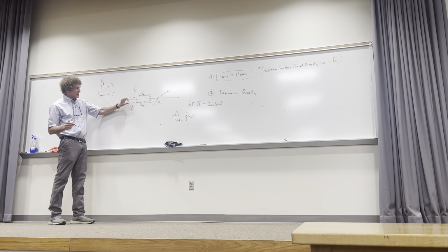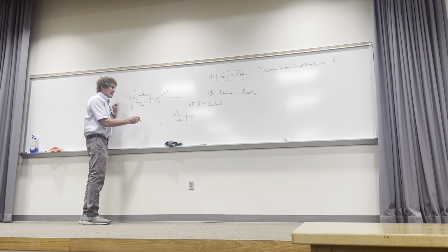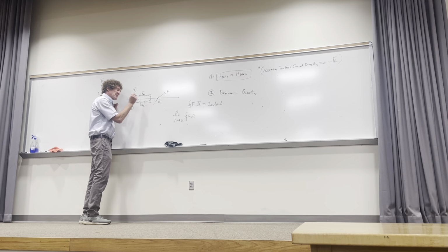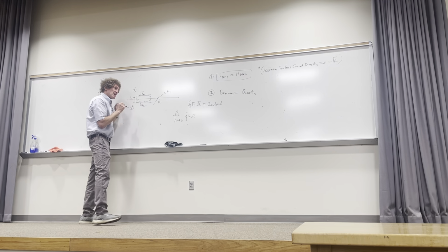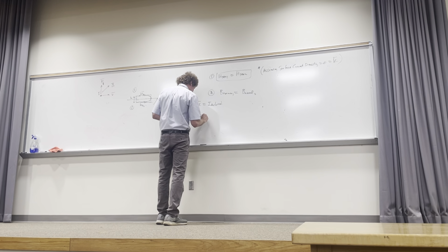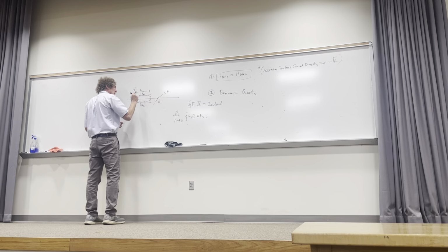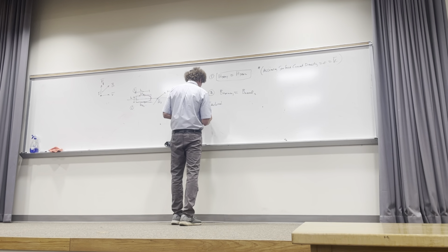And by the way, this thing's symmetric. The same amount is above as below this boundary. And we're going to let this h value collapse down to 0. Then when we do the integral of H dot dl around here, I'm going to assume there's no surface current density where this problem needs to be changed. But then what we do is find that we have H tangent in region 1 times, call this length L here, times L, and it's minus H tangent in region 2 times L.